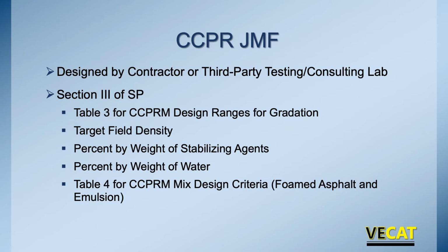They'll develop the gradation, the target optimum moisture content, how much additive may be needed, 1.5%, how much stabilizing agent, 2.5%, 3%, and they put it all together and submit it to the department.